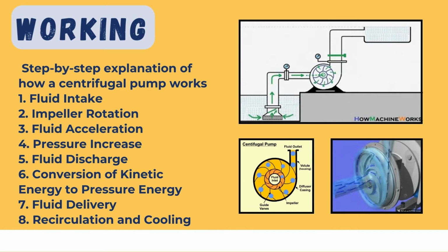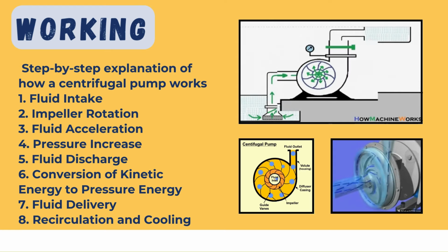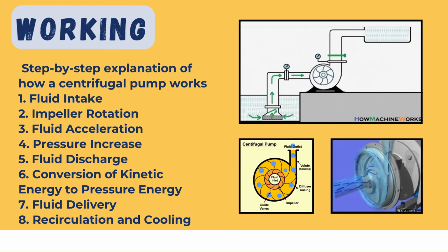After the impeller rotation comes the part of fluid acceleration. The rotation of the impeller imparts kinetic energy to the fluid, causing it to move from the center point towards the outer edge of the impeller.